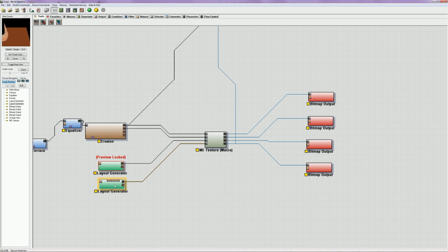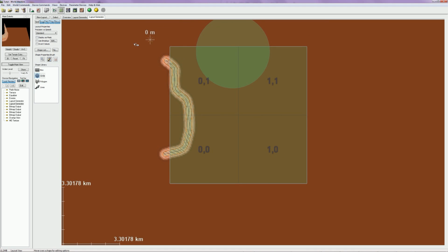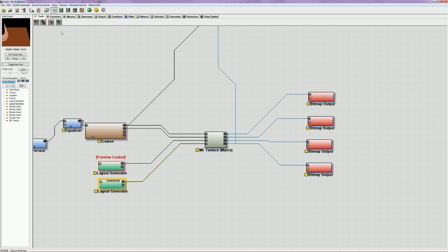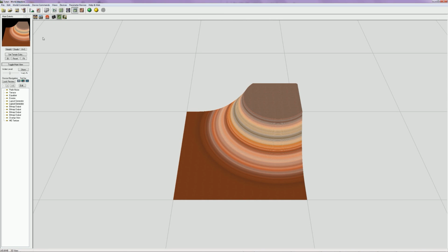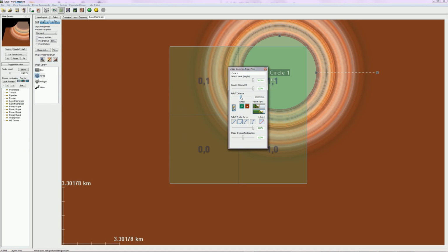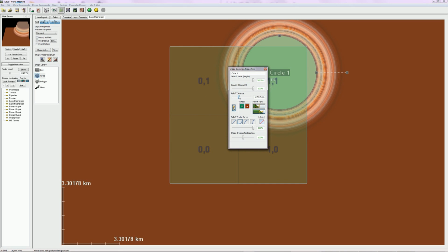And then to get rid of trees in a certain area, you can just draw any sort of shape you want. And then you move it over the area you want to clear of trees, and double click. Then just edit, increase the falloff distance. You don't have to decrease this all the way, just do semi-decreased.